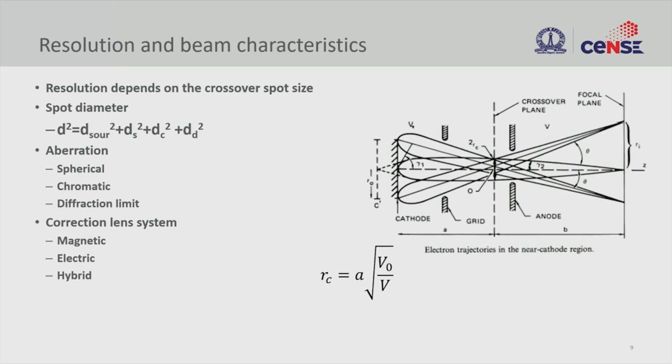The next thing is the resolution of these beams. What actually determines the resolution? In optical we said lambda over NA, times K. Here we discussed NA, we discussed lambda, and also K, how the process determines the resolution. So let's look at what determines the resolution here. First of all, it's a pencil beam.